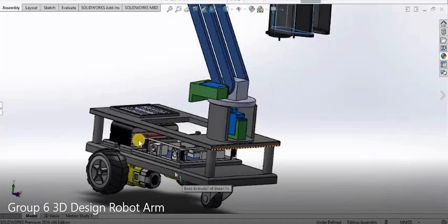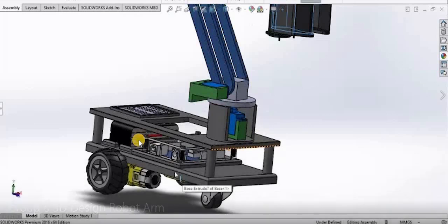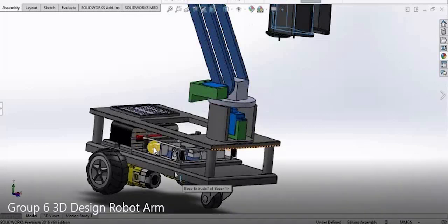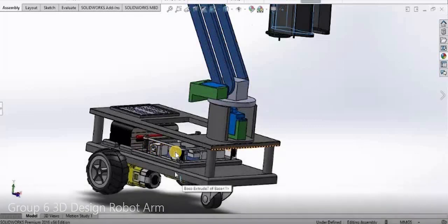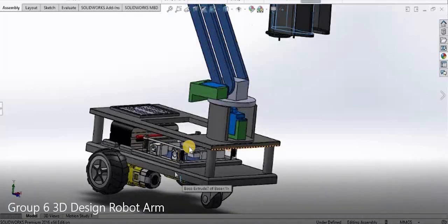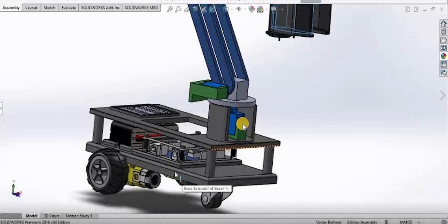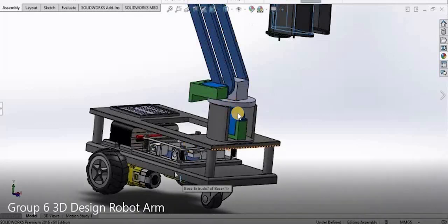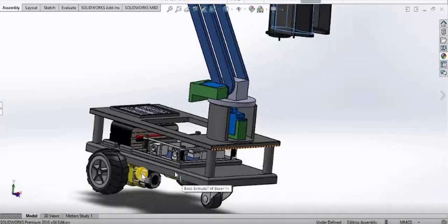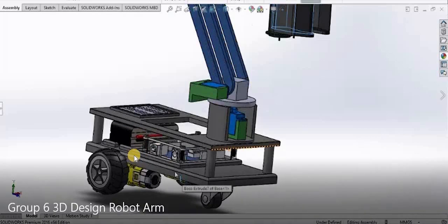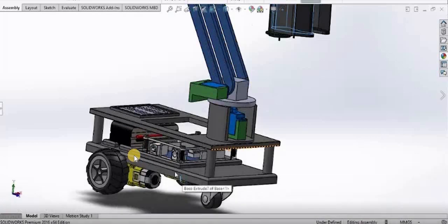And next, why do we think we need two power supplies? This is because if we just solely depend on the power supply from the Arduino Uno chip itself, it is not sufficient to provide power for 4 servo motors and 2 high RPM DC motors, and the battery will drain quickly, so it is not convenient for us.